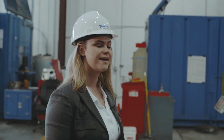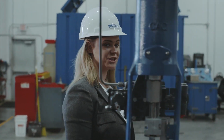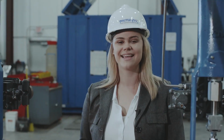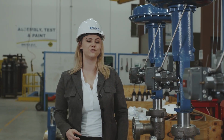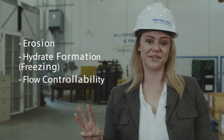Drilling chokes are employed to control high pressure fluctuations during the well drilling process. Injection chokes are usually used to control flow rate and back pressure in the pipelines going into the injection wells, including gas and water injection systems. A production choke is typically used for well optimization or to reduce the wellhead pressure to a level that is safe for transportation. All choke valves face three main problems: erosion, hydrate formation or freezing, and flow controllability.